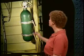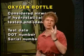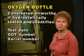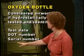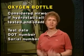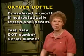Now, how do you know if an aircraft oxygen bottle can be considered airworthy? Well, it has to have been hydrostatically tested, and it needs to have 3 things stamped on the cylinder near the neck of the bottle. Those 3 things are the test date when it was hydrostatically tested, the DOT number, and the serial number of the bottle. What does not have to be stamped up there is the manufacturer's name. The manufacturer's name is not one of the required 3 items.